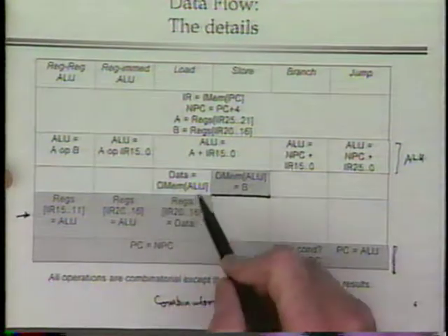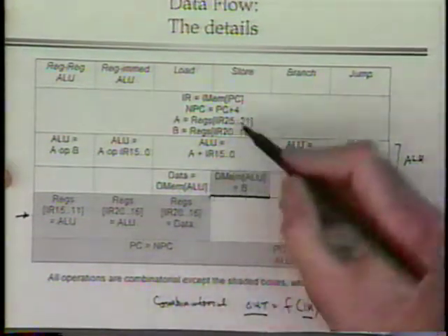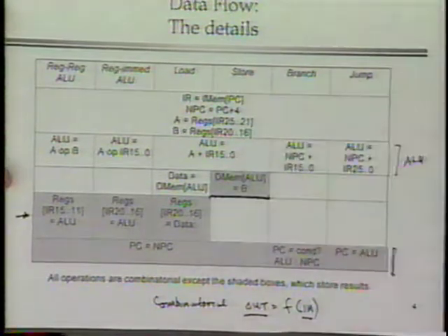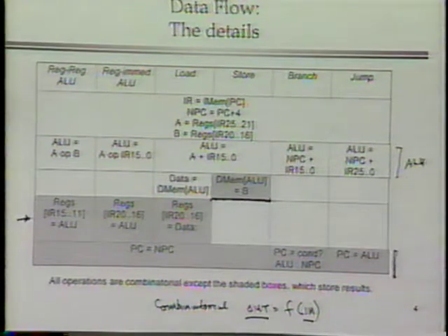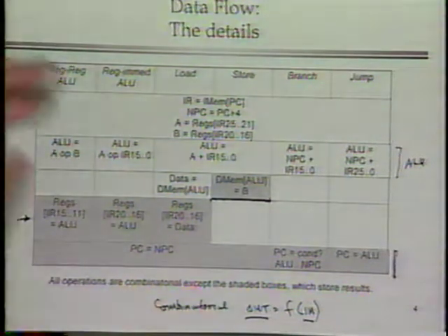Now, in fact, for at least complicated memory systems, it's not that simple. In most memory systems, there is clocking, and it may in fact be a multi-stage memory system that has a cache and virtual memory and other stages. So this is a simplified view of how main memories work. It's not so much a simplified view of how registers work, and registers are just memory after all. The view is that as soon as you change the address coming into that register or memory, a little while later you'll get new data coming out the bottom of it. So it's that model of memory reads that I'm trying to use.